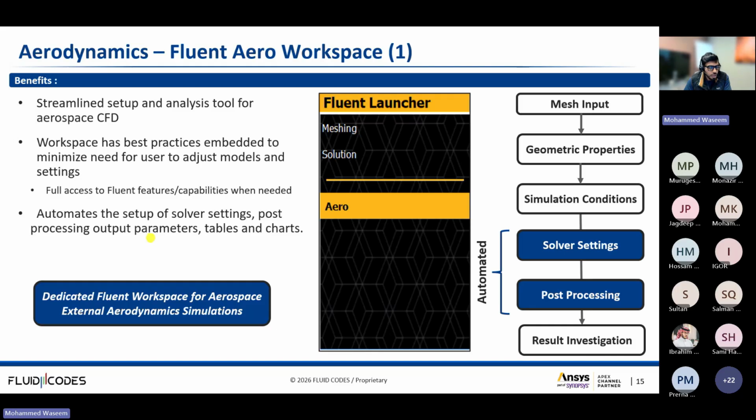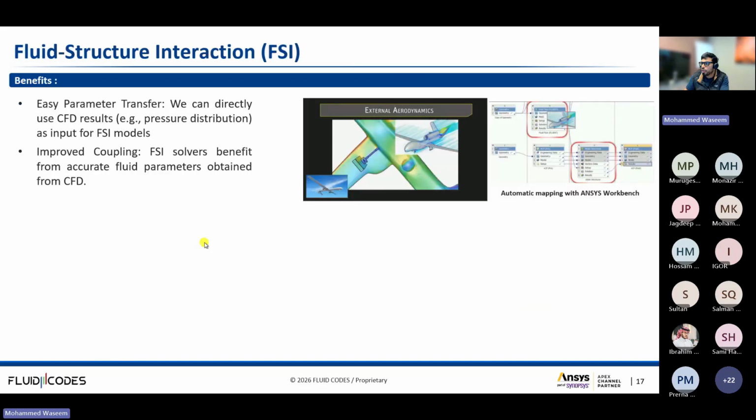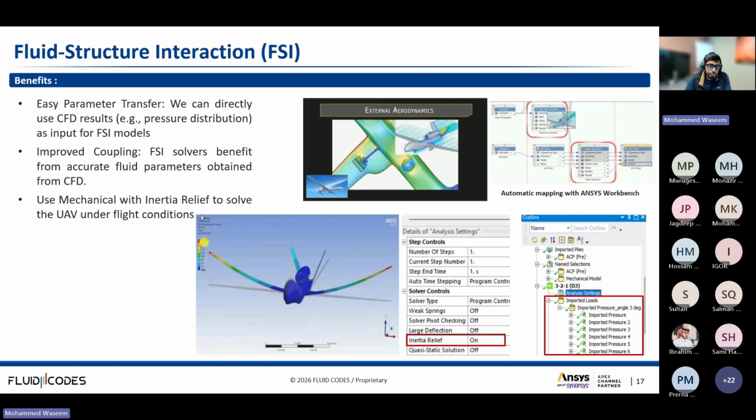Yeah, true. It's a nice question. Let me answer this one. If you want to perform a CFD simulation, particularly FSI, you can couple the CFD results directly to the structural part using this coupling, which is very straightforward. Normally, if you want to work as different teams, CFD files are huge, and you cannot pass the CFD files every time to the structural team.